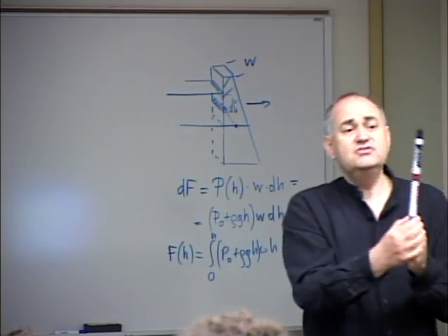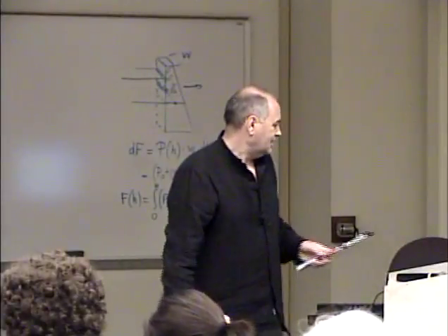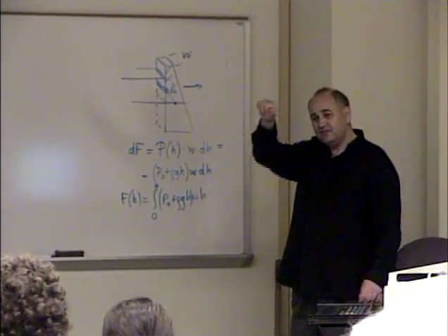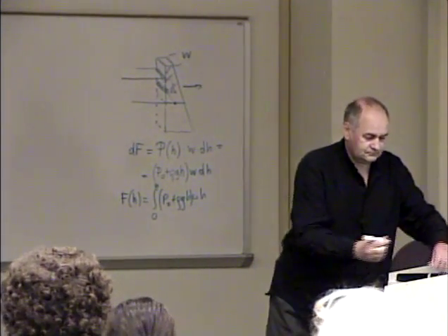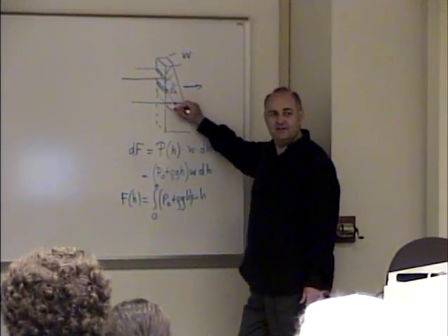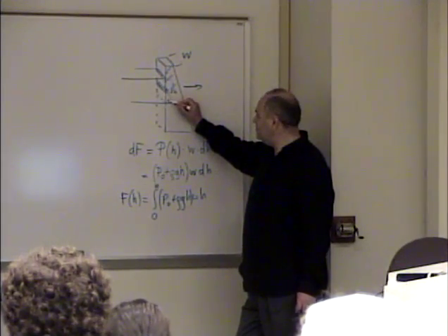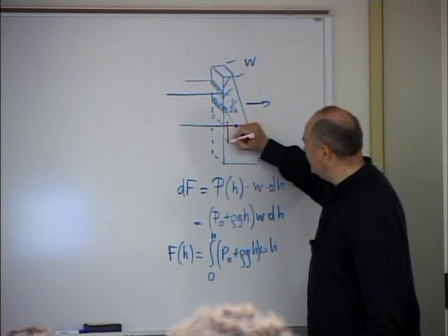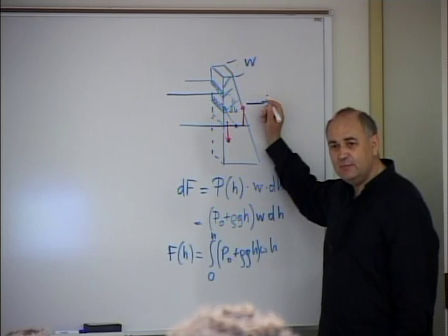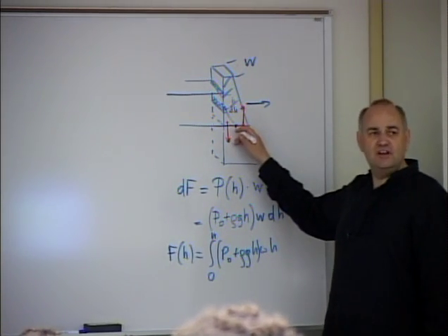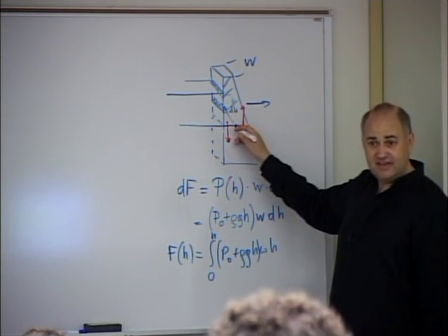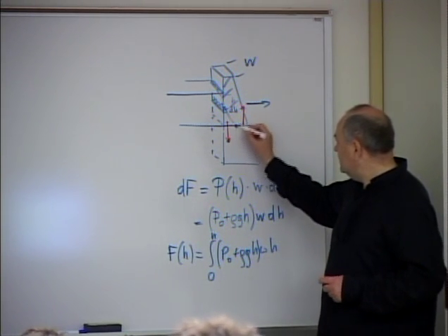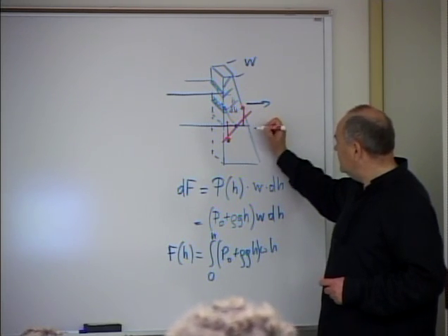Yes, so the internal interaction is stronger, and that internal interaction results in a torque balancing that external torque, which means that the internal torque has to be in this direction, right? Which means that this part of the bottom of the dam is doing what to this side? Pulling it down, correct. And this side is pushing it up with opposite forces. And over here you can drill a hole again. It will not affect anything. So if you want to make a corridor in the dam, it should be in the center, because that part doesn't do anything. The distribution of the tensile compressive stress is like that.